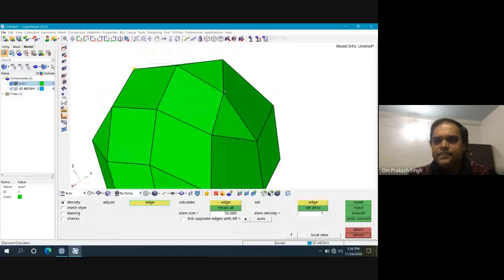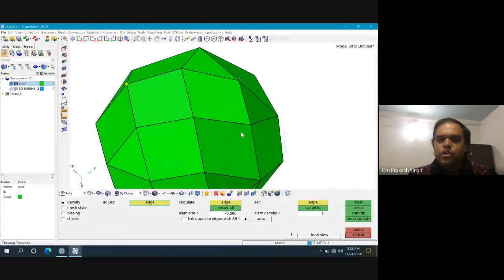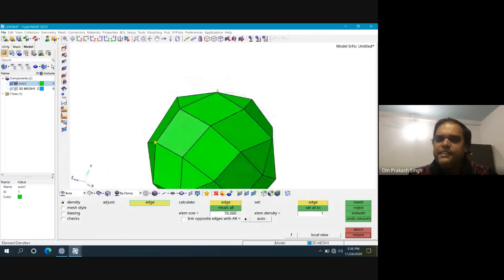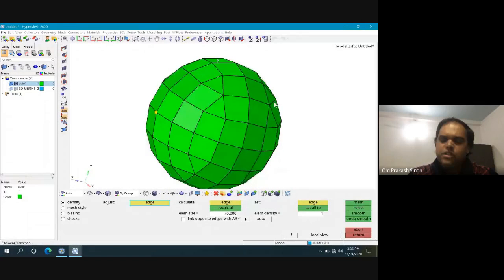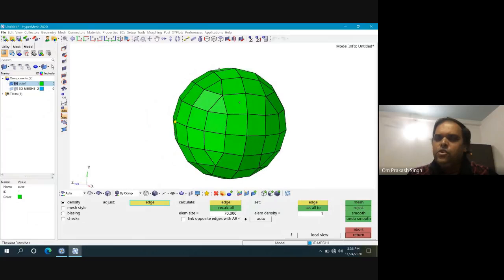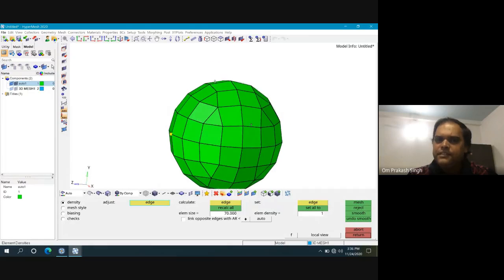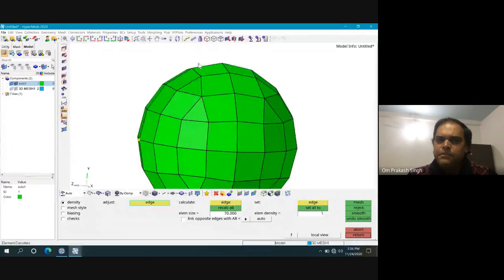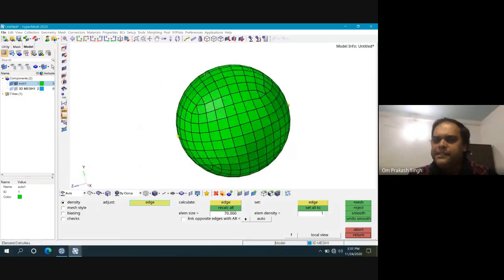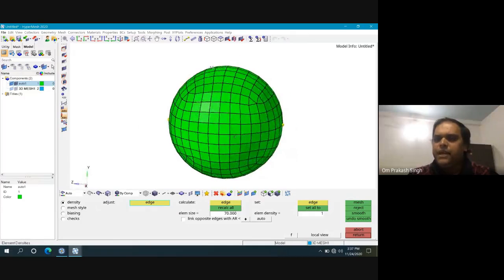But today I'm just discussing how. So now this is not the correct mesh. So what we'll do is increase the mesh size, or refine a little bit. If you keep on increasing the number of elements, slowly it will capture your geometry. Let's say I increase the number of elements on this, and you see it becomes better and better. So the number of elements is increasing, so it's capturing my geometry.